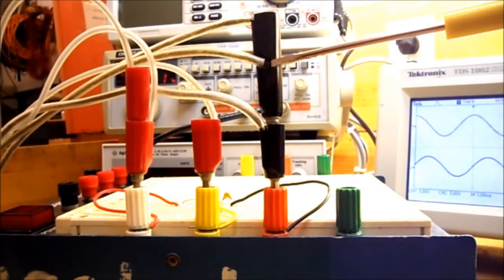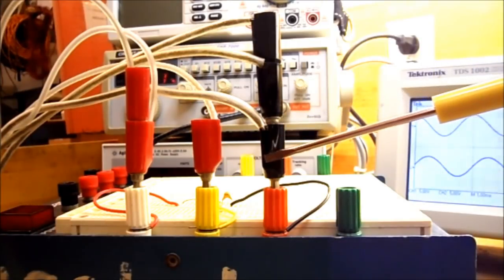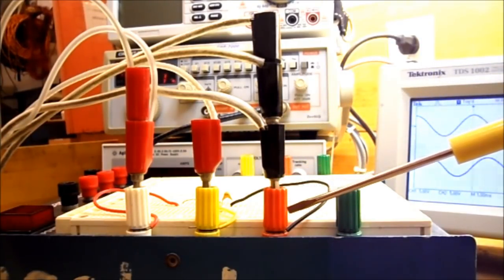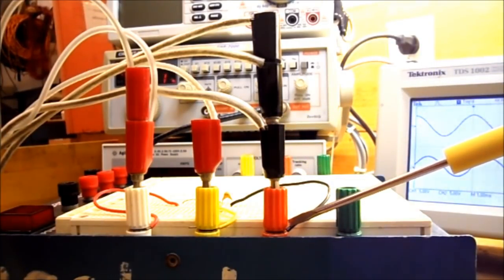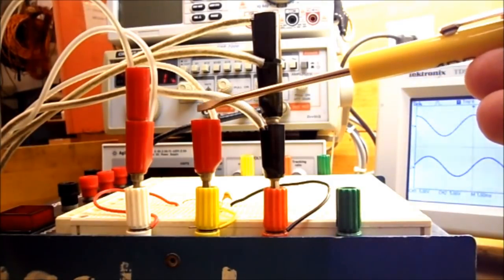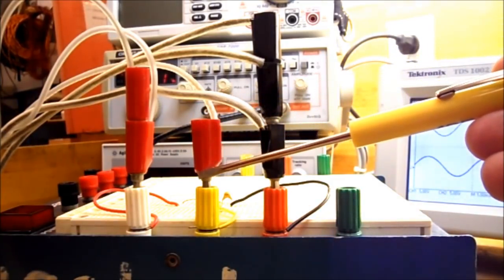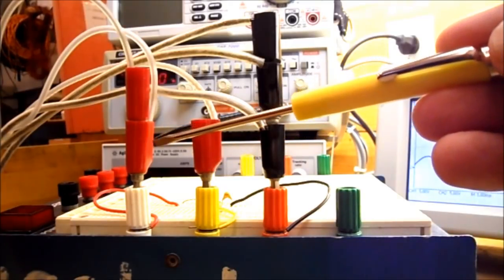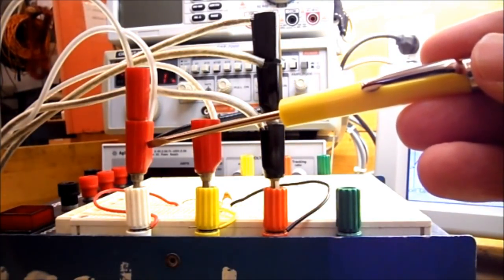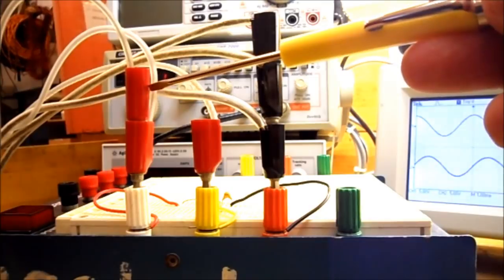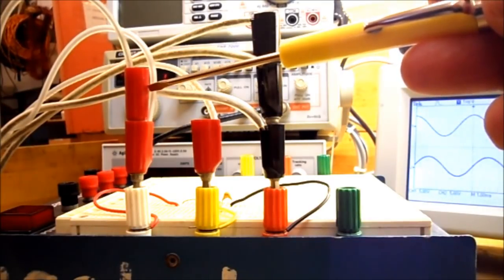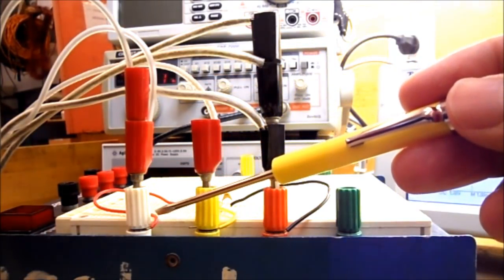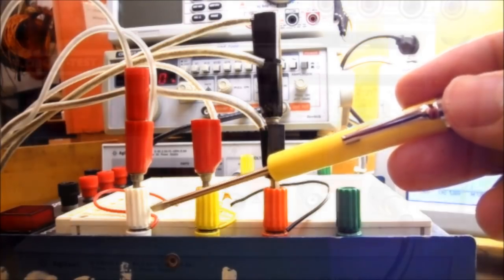Notice all the black leads stacked together, and they go to the bottom of my capacitor, which was the black wire. I have channel 2 of my oscilloscope going to the yellow terminal, which went to the midpoint between the resistor and the capacitor. I have the input from my function generator and channel 1 of the oscilloscope going to the red wire that went to the top of my resistor.